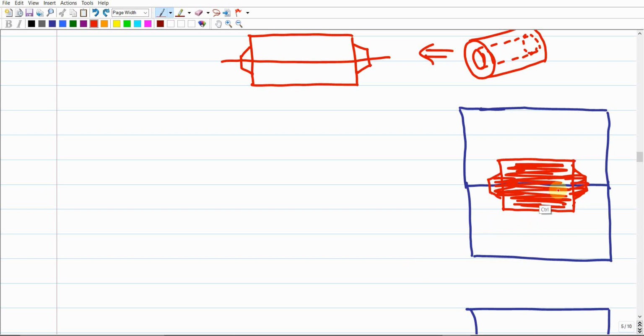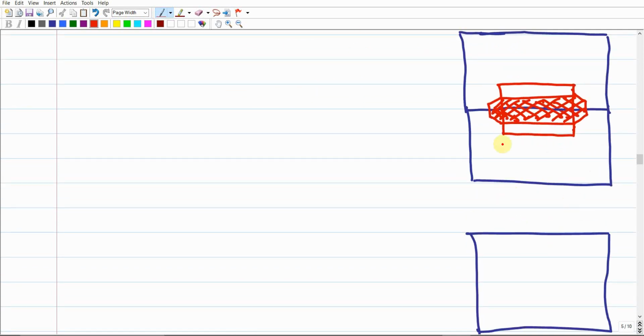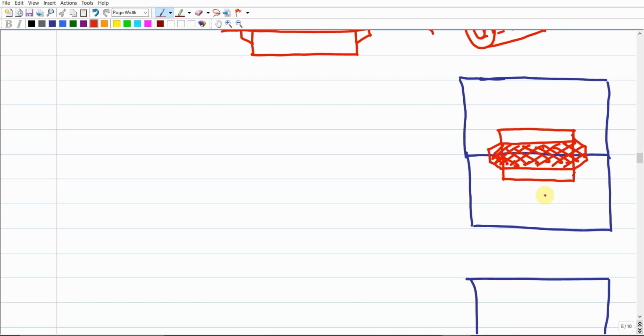If this is the casting, there should be a core here that is used to form the internal opening. This is the core in the middle. This is how the casting and the core are located. Again, the core here will be horizontal. It means there should be a pushing force coming from the molten metal acting on the core, and then the core keeps pushing on the cope. In the meanwhile, there is a pushing force from the molten metal acting directly on the cope itself.